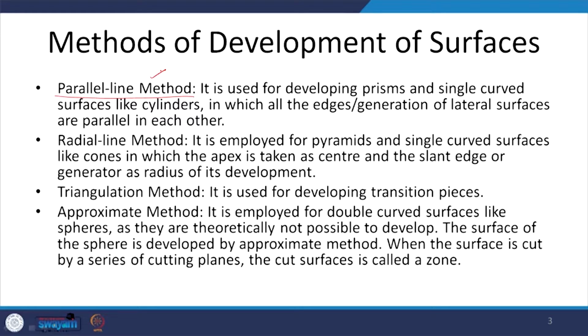If you recall what we were talking about when we were doing the orthographic projections of prisms, we said that in most likely cases we will always see the rectangular surfaces, even when they are cut, or in elevation, or depending upon the positions. We will largely see the rectangles because that is what is connecting the two bases.